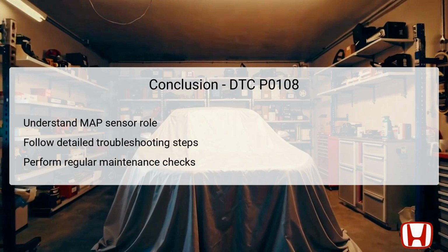In conclusion, understanding the role of the Manifold Absolute Pressure MAP sensor is essential for effective engine management in the Honda Accord models from 2012 to 2017. The activation of DTC P0108 indicates high voltage in the MAP sensor circuit, requiring methodical troubleshooting to identify the root